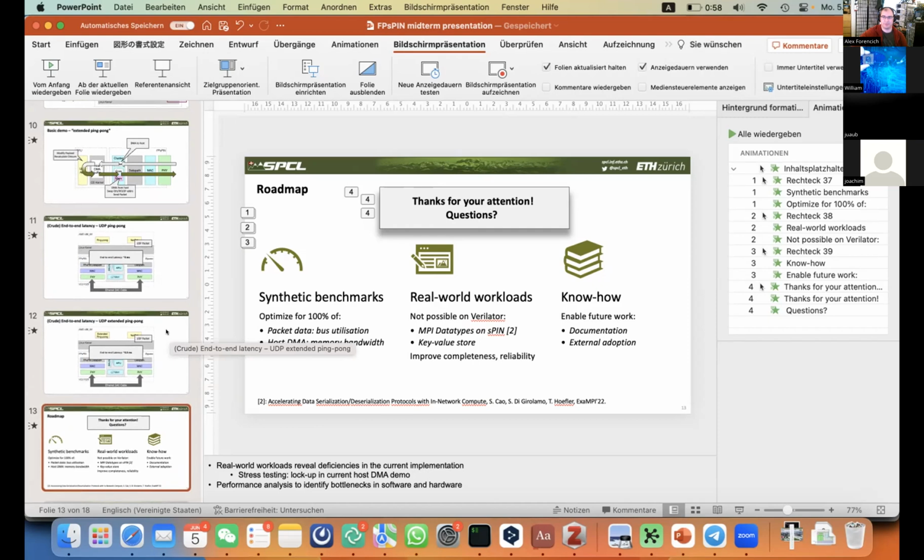Yeah. Right. And I guess that's also one of the things of FPGA versus ASIC, right? With an FPGA, you can actually test this stuff out in hardware without too much difficulty. Versus ASIC, that's a lot of dollar signs and a lot of months waiting for a tape out to come back. And then when it doesn't work, it's a nightmare that you have to spin the chip again. Yeah, with Corundum, if something doesn't work, okay, let's add an ILA and figure out why, and then rebuild it. And within a couple of days, you figured it out.